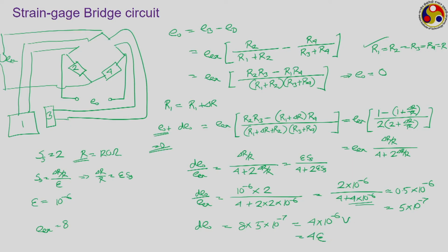So, the change in output voltage is the same as what we got in the case of the ballast resistor. But the advantage here is that there, with the ballast resistor, we were trying to compare in terms of a potentiometer, where initially 120 ohm was already there, and with respect to 120 ohm we were trying to get a voltage value. But here we are not at all comparing this particular value with respect to this one, rather we are only sensing this amount of voltage.